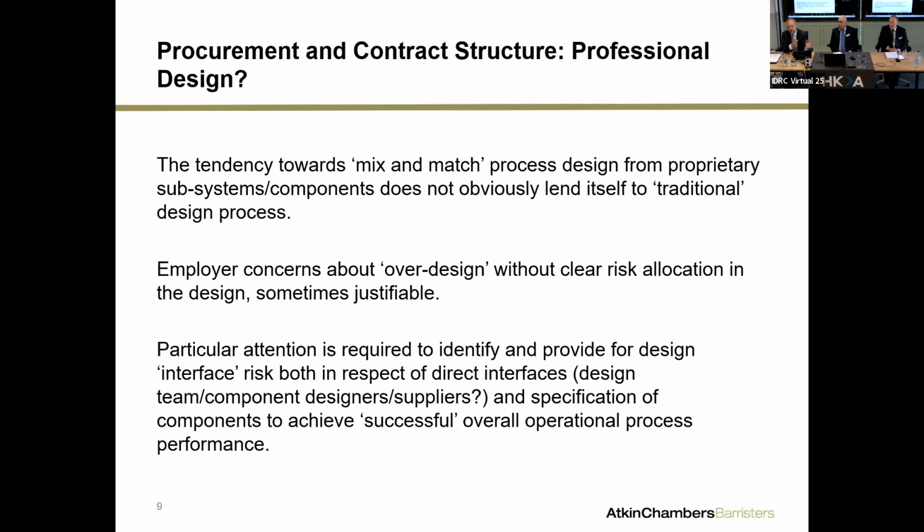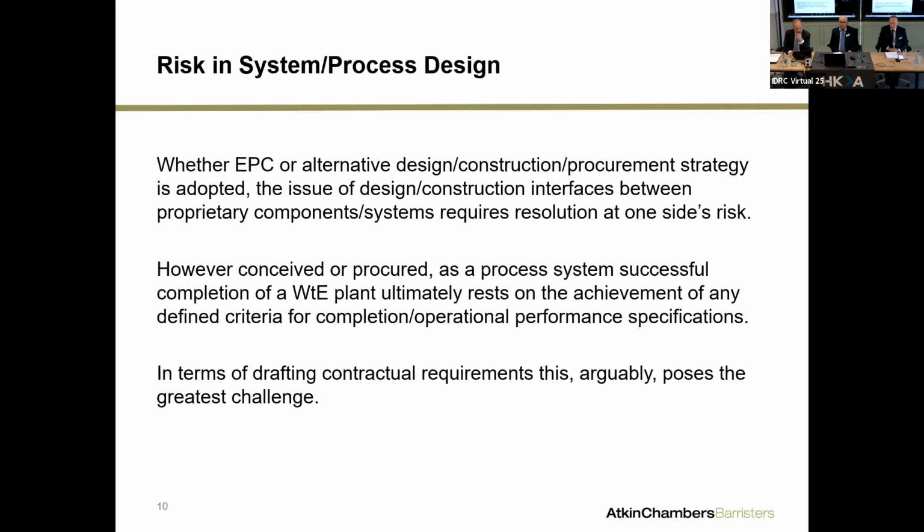But of course, when you do that with 17, 18, 19, 20 subsystems, what you're actually doing is taking 20 different design interfaces, potentially construction interfaces as well. And unless you think it through carefully, it's quite unclear where the responsibility and risk lies in that aspect of design. So from the advisor's perspective, you'll think about how you're going to apply that risk. Who is going to take overall responsibility for that? One of the ways it's dealt with, I've seen, and I don't think it's really the answer, but it's probably the best we've got, is to try and define by performance specification what you want at the end.